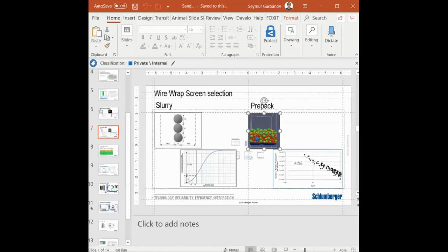Big companies' methods of controlling sand in Caspian Sea oil and gas fields. So BP, when they just started to produce from the ACG, tried different ways of sand control. Starting from just standalone screens, expandable screens, they have run prepacked screens as well. So eventually what they came to is that the gravel pack is the best fit option for the ACG fields. So they are gravel packing all the open hole wells.